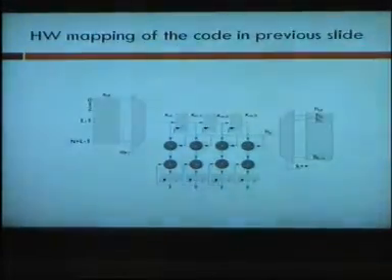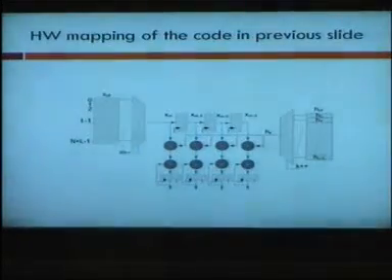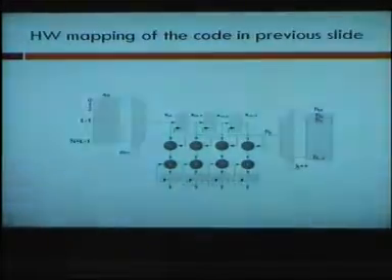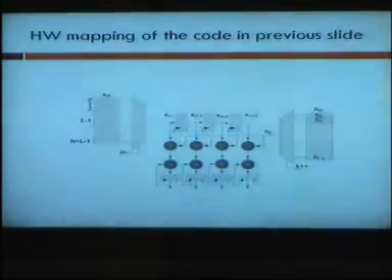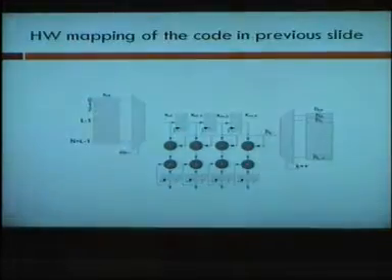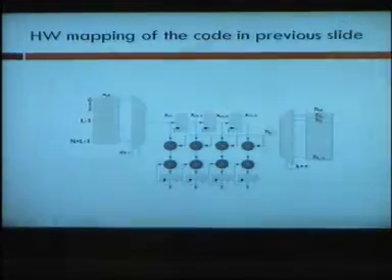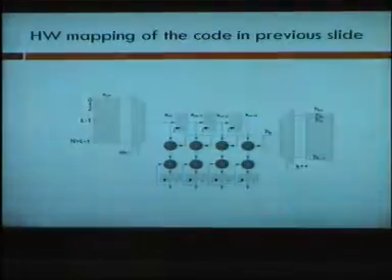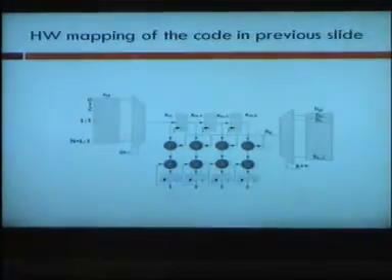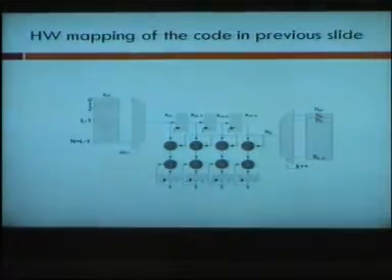And definitely it depends upon the resources you have on your device, but it's in your hand. You sit down, you do your calculations, know at what rate you are getting the data and at what rate you have to produce the output, and then you say, okay, I think 4 multipliers are good enough to give me the required performance. So this is the difference between doing things in software and implementing things in hardware, with the same algorithm,